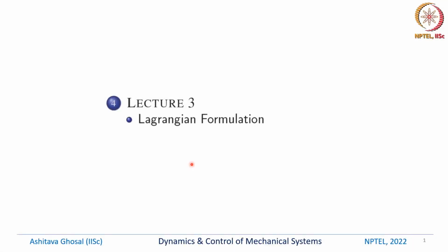In the last lecture, we looked at the Newton-Euler formulation. The basic idea in the Newton-Euler formulation is propagation of velocities and accelerations from the base link to the free end, and then we use Newton's law and Euler's equation to compute F equals ma and torque equals I alpha plus omega cross I omega, and then we propagate these forces backwards to the base. And to find the joint torque, we take the z component of the moment.